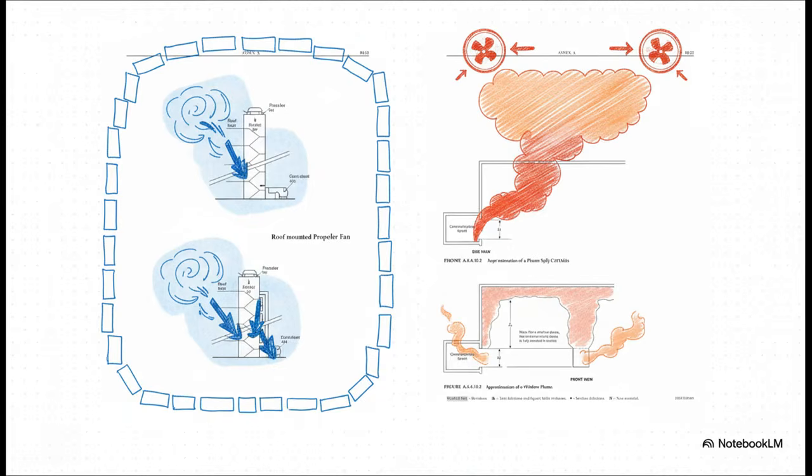And here's what those two strategies look like. On the left, that's stairwell pressurization, a classic containment strategy. You're pumping air into the stairwell to create a higher pressure that acts like an invisible barrier, keeping smoke out. On the right, that's a big open atrium. You can't just pressurize the whole thing, so you have to manage that smoke plume, pulling it up and out of the building to keep the floors below clear.